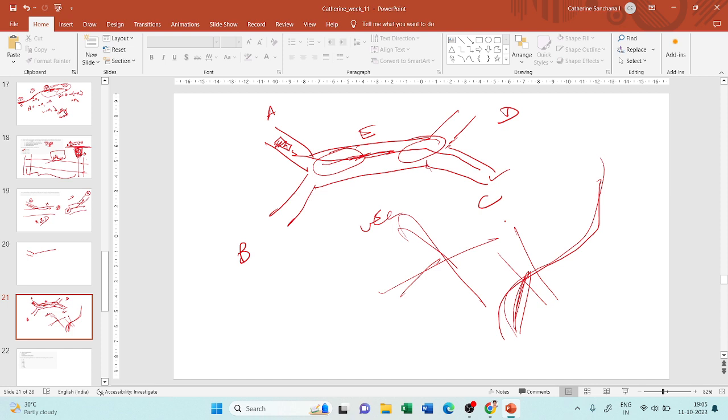So this is the weaving action. It is a combination of both merging and diverging. So what is a weaving section then? The weaving section is obviously the location where this movement takes place. So basically E is my weaving section.